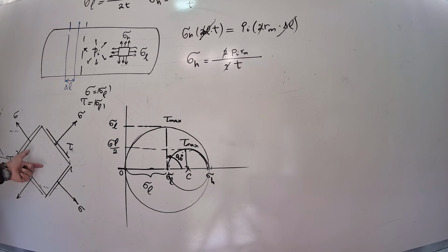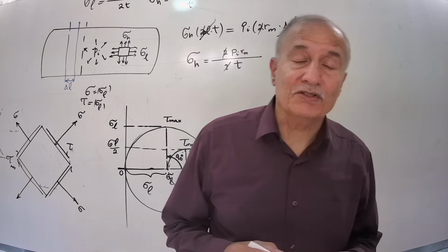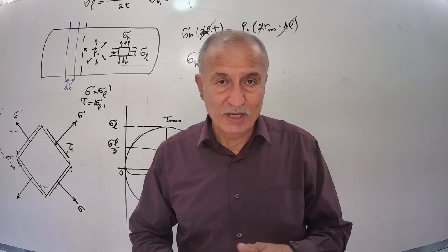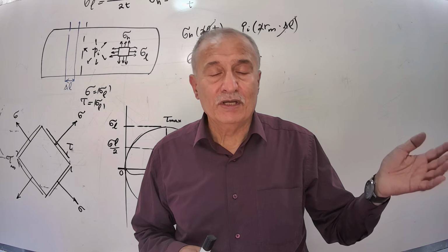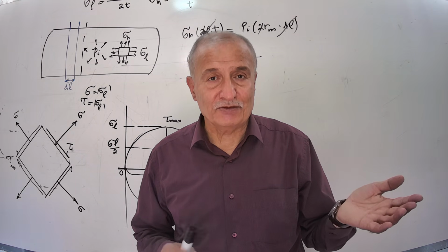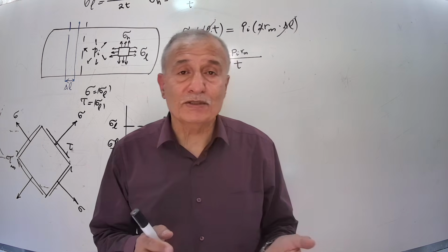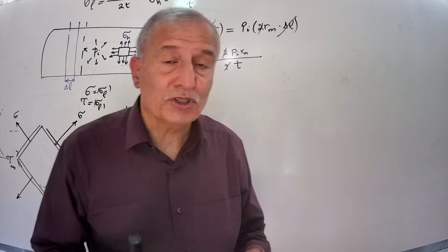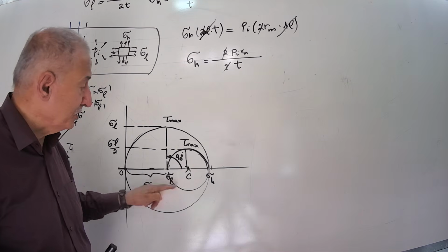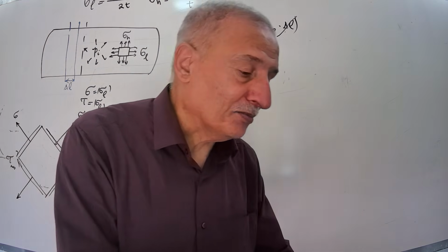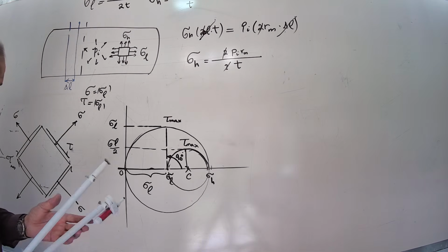And then maybe this is the worst case scenario for designing these pressure vessels. Any designer must consider both cases. First, design based on maximum normal stress, which is equal to sigma hoop, and then consider based on the maximum shear stress. But maximum shear stress in this case is not this one in the two-dimensional Mohr circle, but in the three-dimensional Mohr circle. Consider sigma 3 as 0 and sigma z.